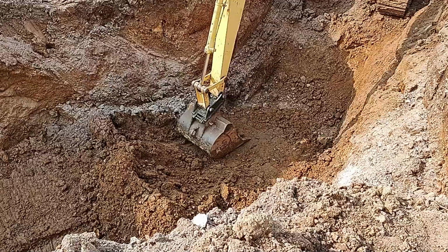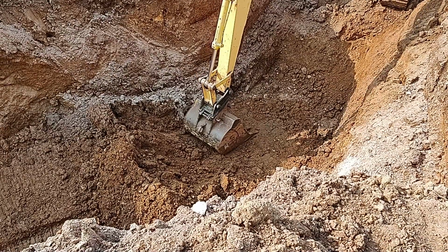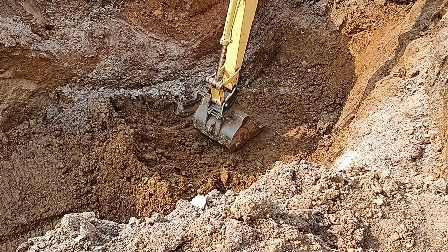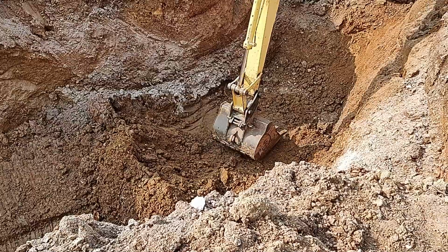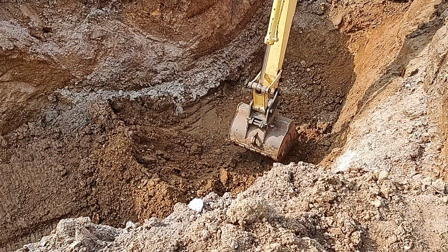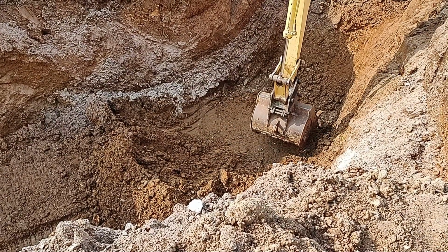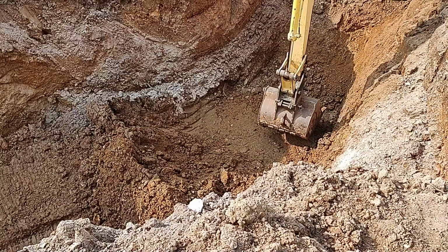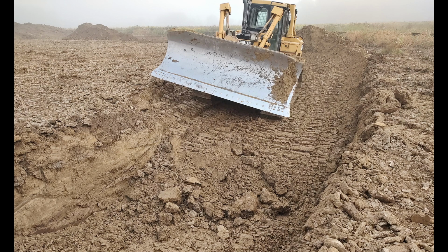It's often necessary to fill and compact the bottom of the core trench using the excavator when it's dug deep like this one. For safety reasons, heavy equipment should not enter the trench where a cave-in could cause them harm. Here the dozer begins to widen and fill the core trench that was dug by the excavator. The excavator dug the core trench about 3 buckets wide, and it went really fast.